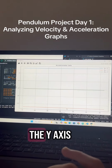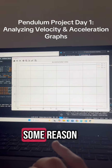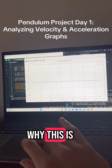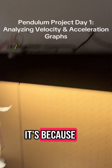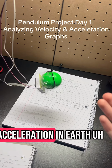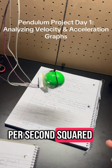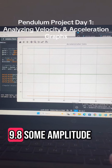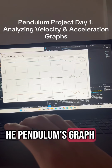Okay, the acceleration in the y-axis, it's at -9 for some reason, even though the pendulum is not really moving. And the reason why this is happening is because it's not an error or anything. It's because, well, gravity has a default acceleration on Earth of 9.81 meters per second squared. So that's why it's reading about -9.8. Some amplitude in it. The pendulum's graph should be moving.